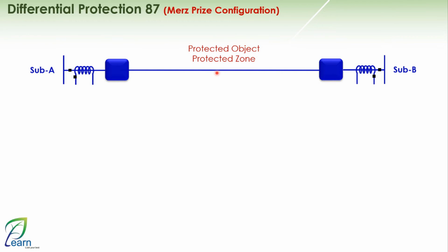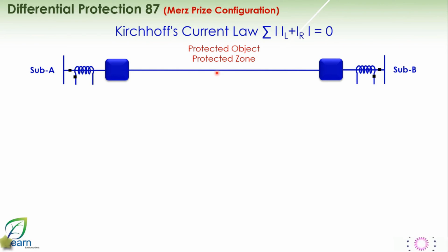So in general, we can say that it depends on the principle that the sum of the currents in my direction equals 0 under normal conditions. The sum of the currents in equals the sum of the currents out, and therefore their vector sum will be such that one, for example, is at 0, and the other at 180 degrees from the first. Consequently, if we sum them vectorially, it will equal 0. Now let's go ahead and build our electromechanical relay and construct the complete protection system.